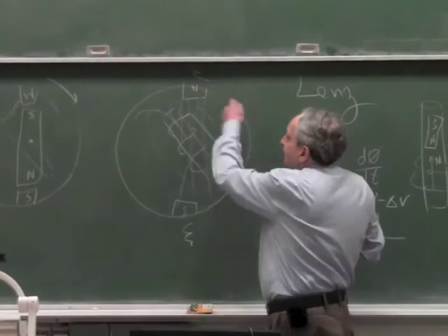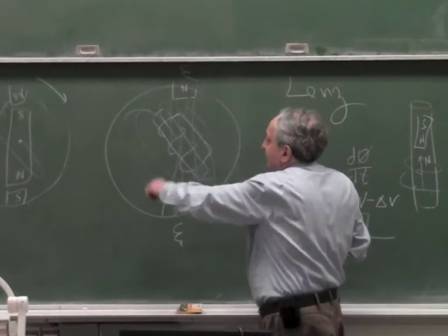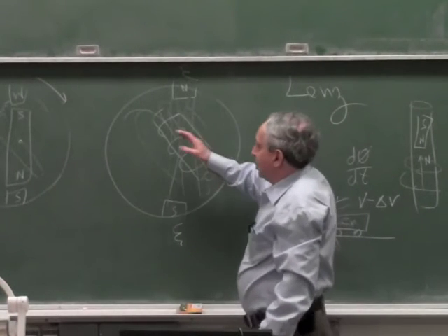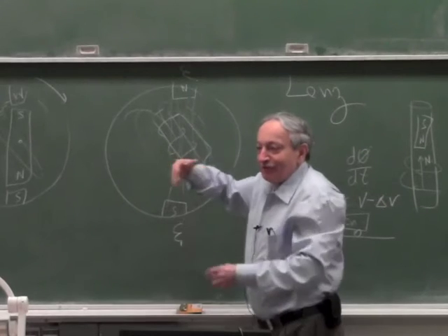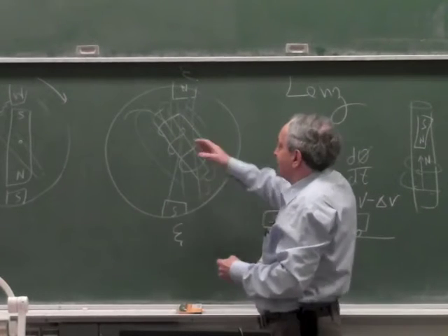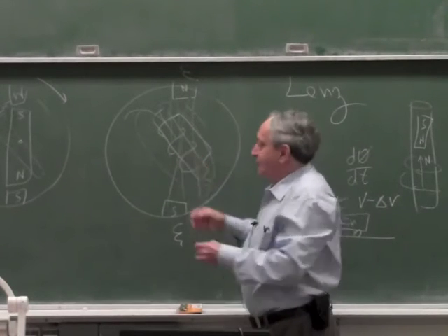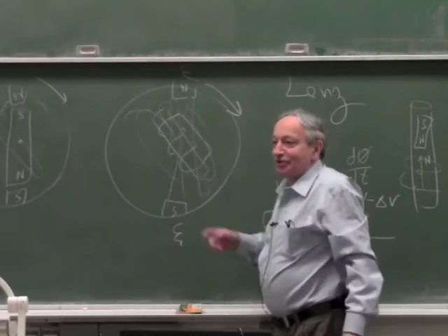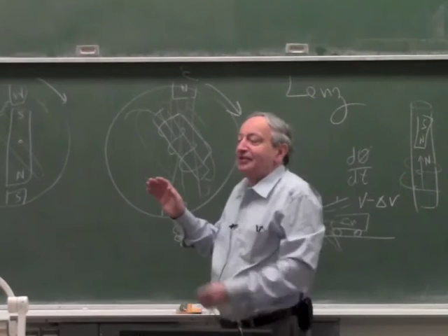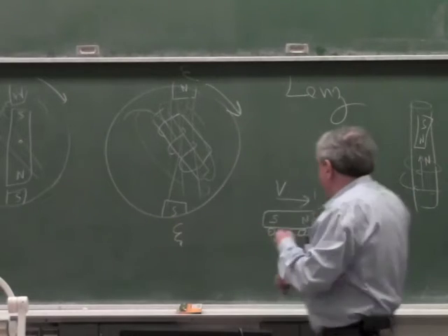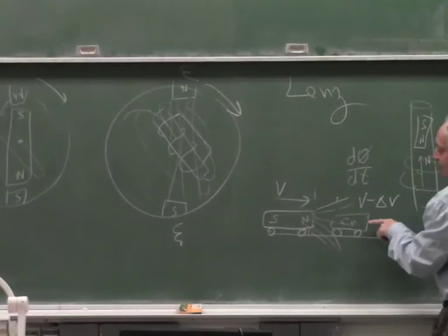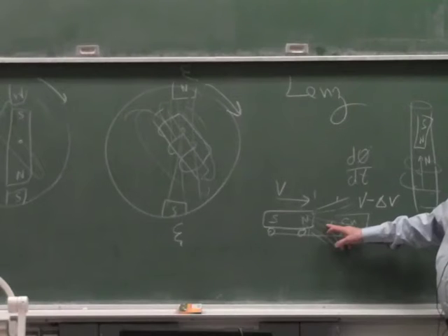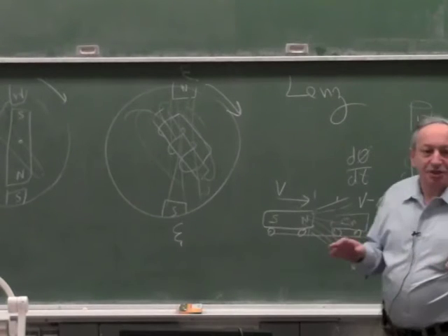But because the magnetic field has to go faster in order to generate a delta F, it looks like the rotor is lagging behind. It's always falling behind, so it appears as if it is being dragged. The rotating field goes faster and this seems to be following, but it's actually not following. It's being pushed ahead with a slip. The same way here, as this is being pushed ahead, it's falling closer and closer to keep the magnetic field changing. Okay? Now, is this explanation clear to everybody?